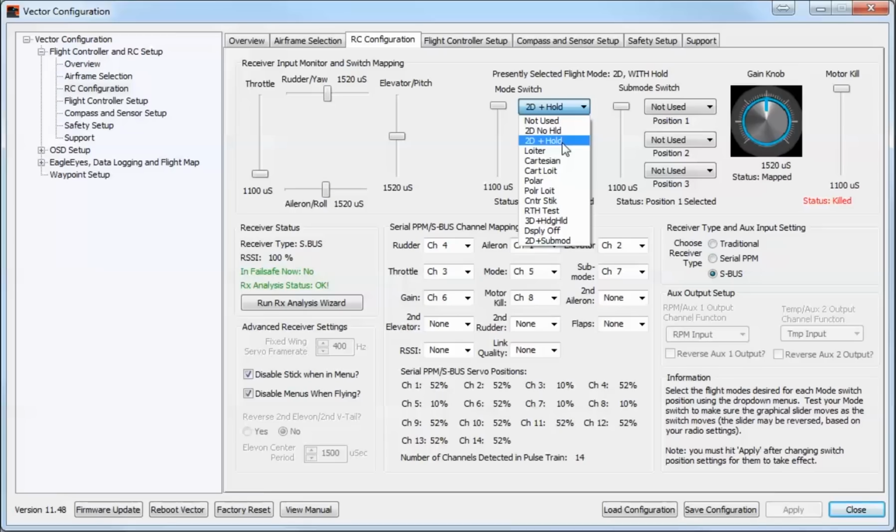If you want to increase altitude, so let's say you want to go to 20 feet, obviously you would either give it a full blast throttle and it will fly up, or you can give it a subtle amount and it will increase. Again, the key is that when you put it back down to 50%, it will say, right, this is the altitude that I'm supposed to stay at. It's still going to get blown around, it's not a GPS mode again, but it is actually going to fix that altitude. So that at least gives you the ability of knowing it's not going to start hitting the ground if it's up in the air.